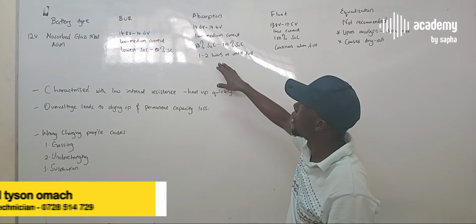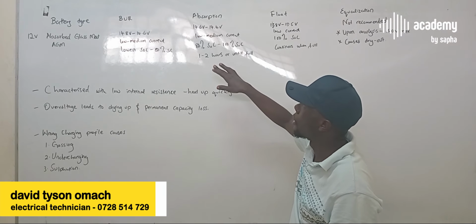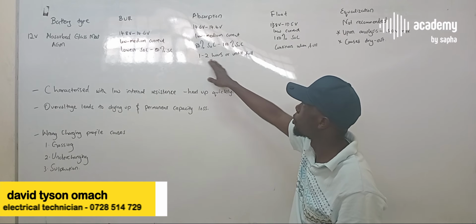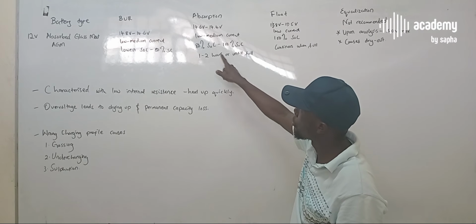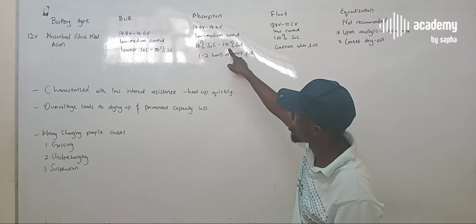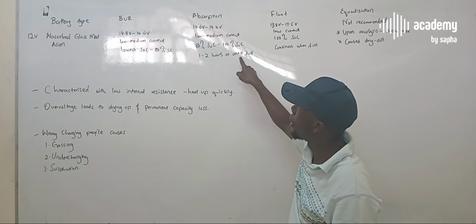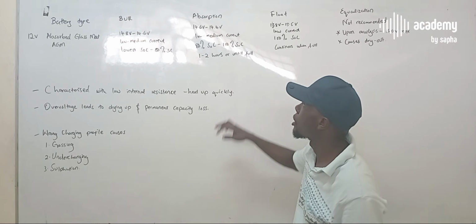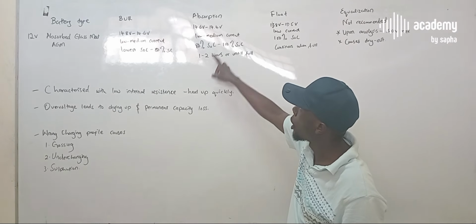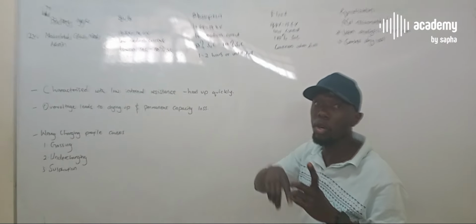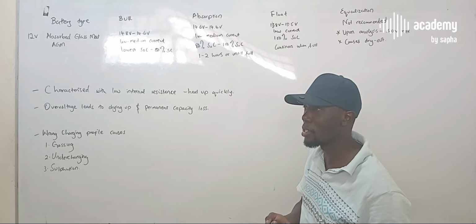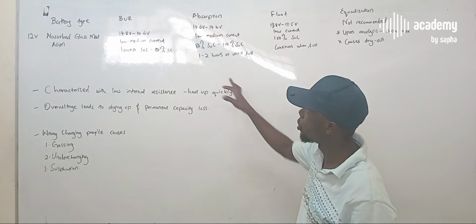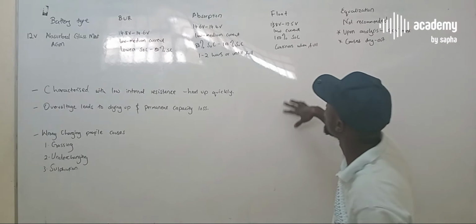And this typically has to occur between 1 to 2 hours, or if getting from 80% to 100% SOC is shorter, that is recommended. When you subject it to absorption for a longer period, it also affects the internal chemical structure of the battery itself, and I didn't want to go too deep into that for now.